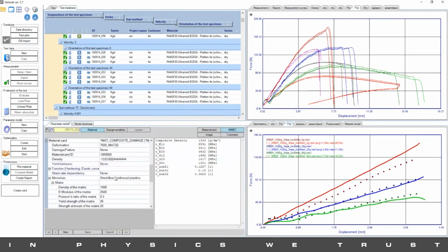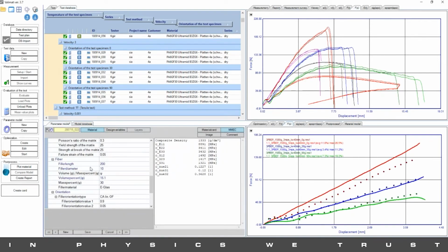So, just to see what is the right value for the fiber content, the fiber length, and the fiber orientation, because that will not change. That's something fixed in the material model. What changes is after the deformation, the plasticity, for instance, or the failure. That's nothing that will change during the simulation. And as you see here, if you use a high orientation, we're clearly in this highly oriented range.